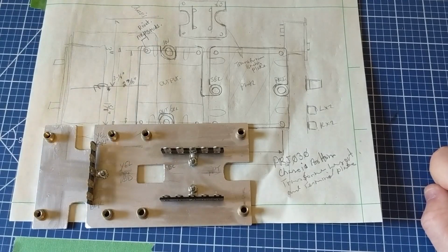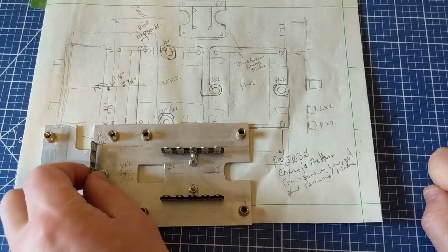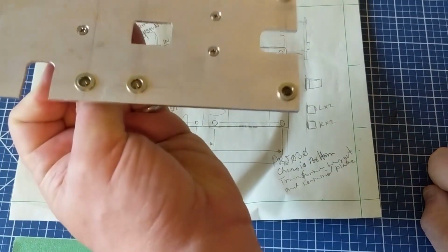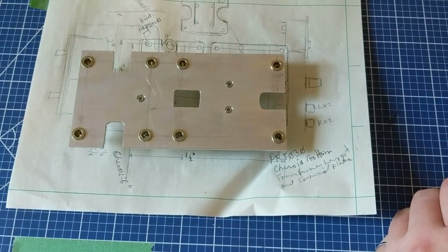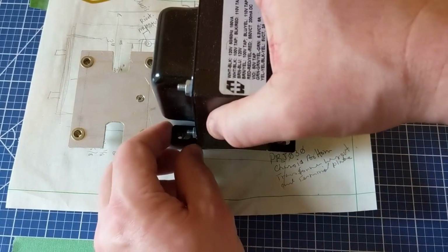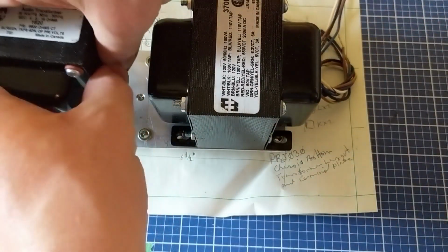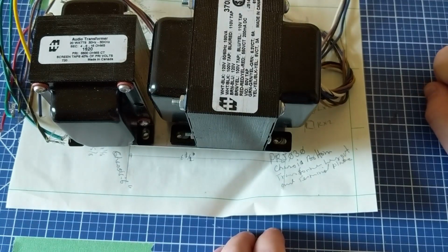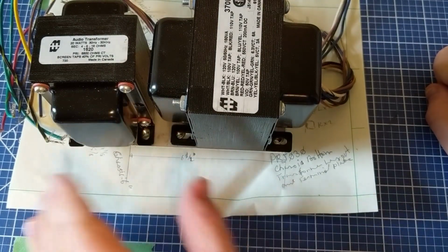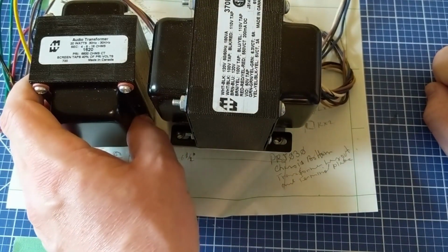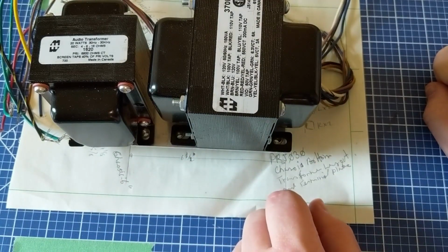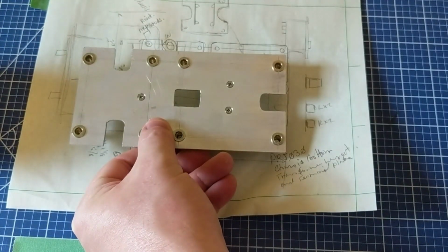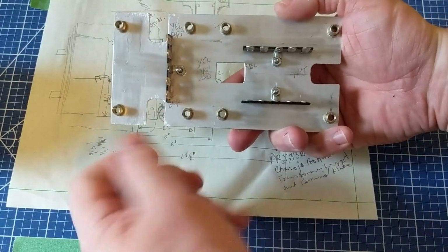For the high voltage point-to-point circuitry, I decided to create another plate that would go inside of the chassis, and this plate is directly underneath the 2 transformers on the inside of the chassis, like so. So the power transformer and the output transformer on the top of the chassis would bolt down to this subplate. It serves a couple of purposes. It stiffens up the upper surface of the chassis a little bit. It means I don't have to worry about nuts and bolts in securing the transformers down, because the plate has threaded inserts already press fitted into it, so they're secured.